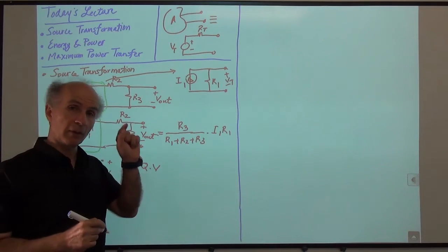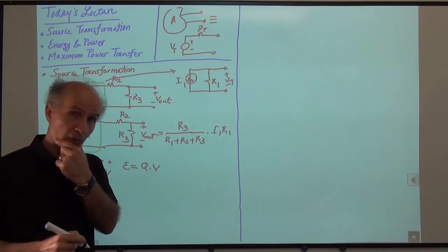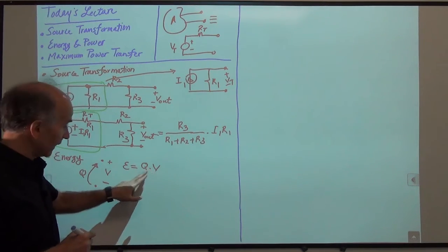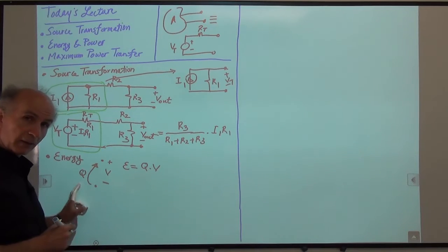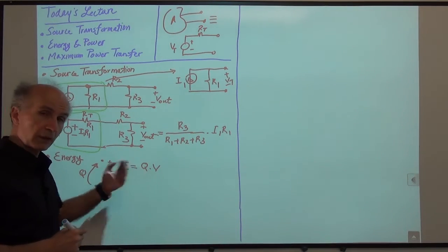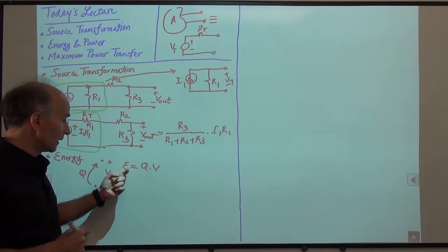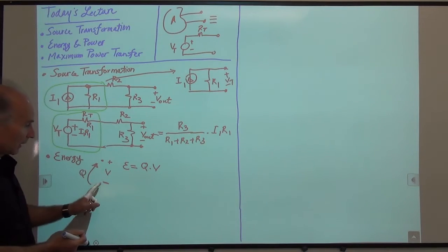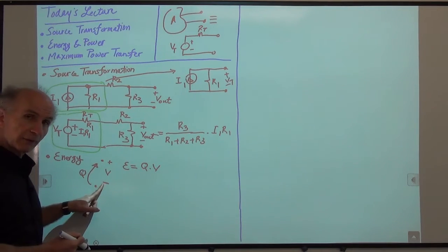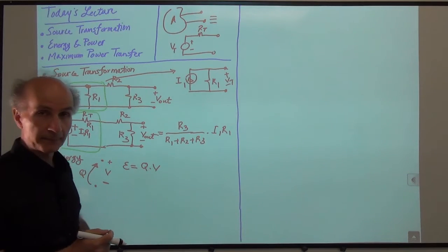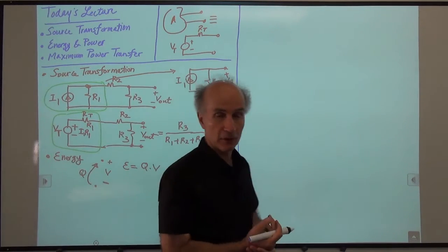When we talked about the voltage at the beginning of this course, we went the other way. We said voltage is defined as the amount of energy necessary to take this charge divided by the charge, right? But now I can just write it like that. So the energy that I have to give to this charge to take it from here to here across V volts of difference is given by the charge itself times the voltage difference. All right, so that's the amount of energy that we have.